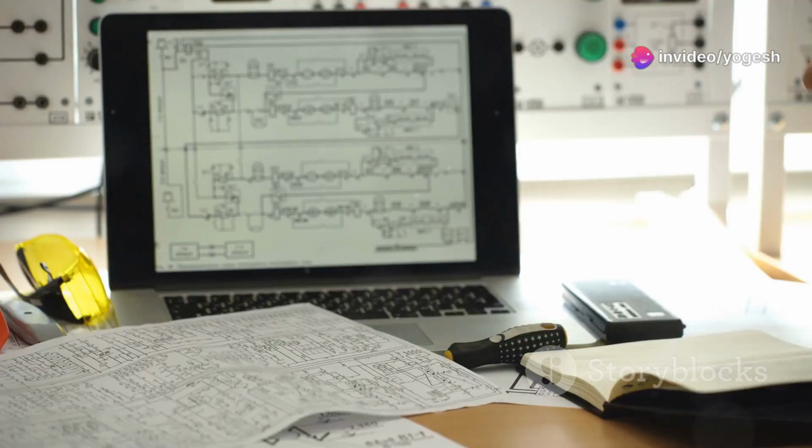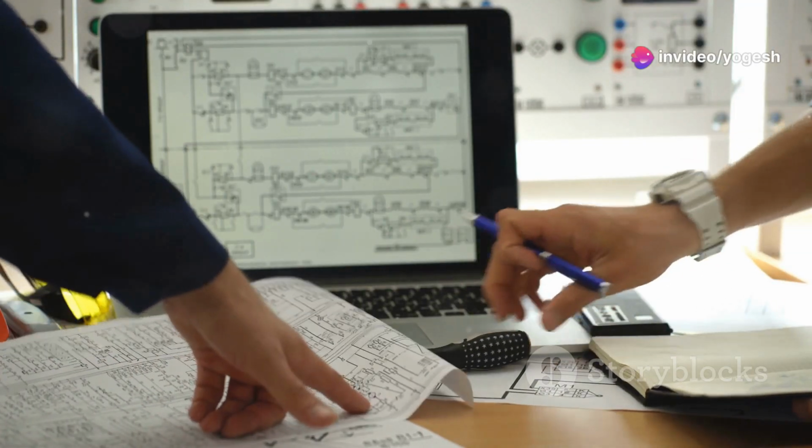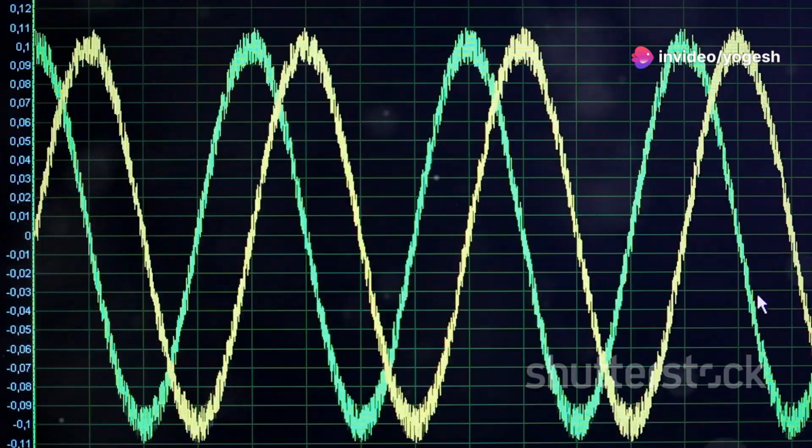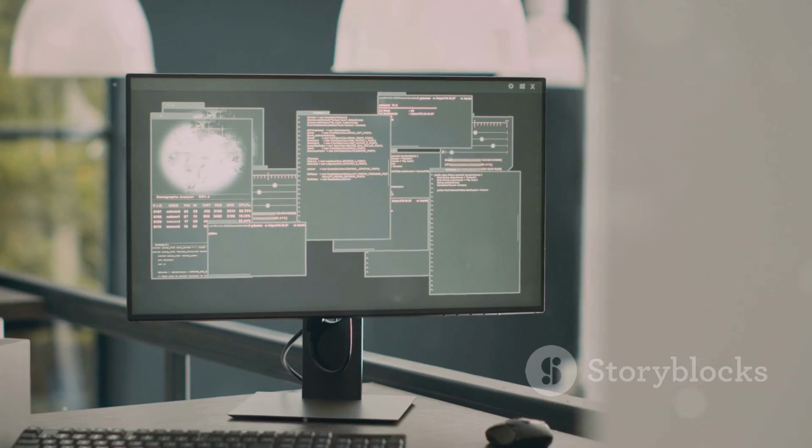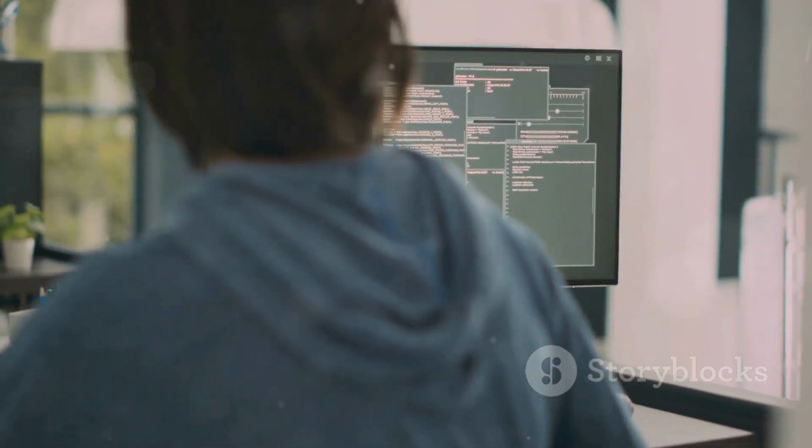The main purpose of the derivative term is to add damping. It helps to reduce overshoot and oscillations. It makes the system response smoother and more stable.